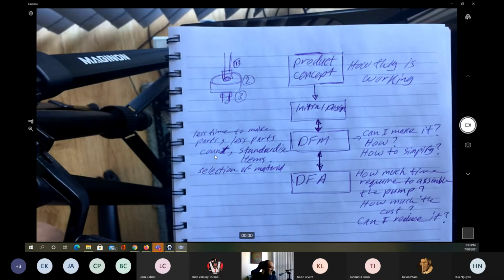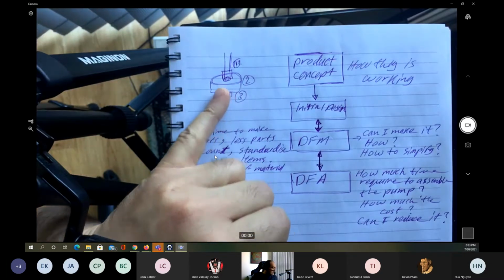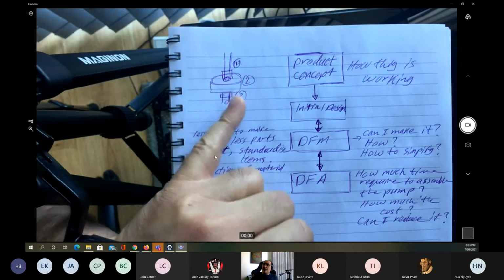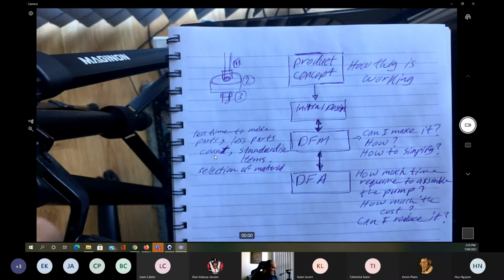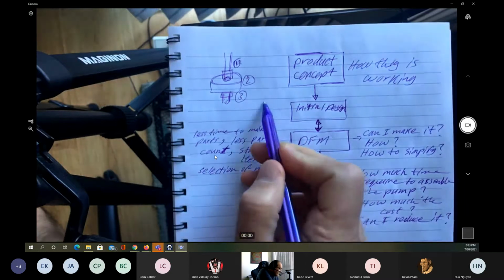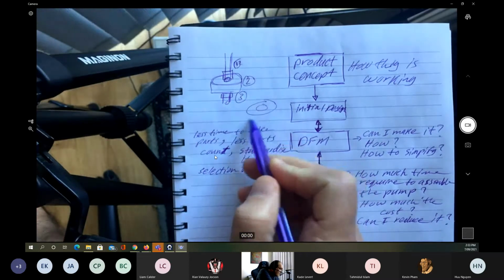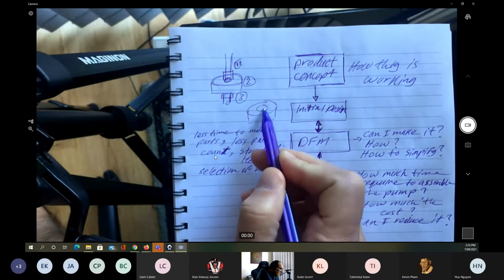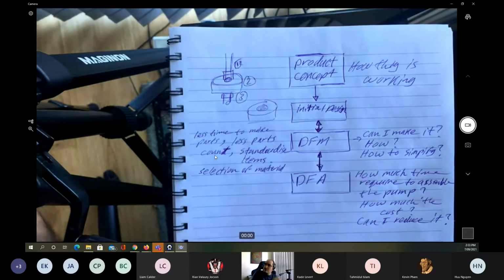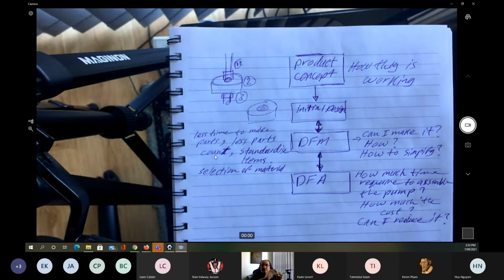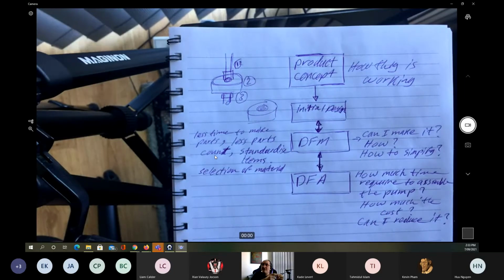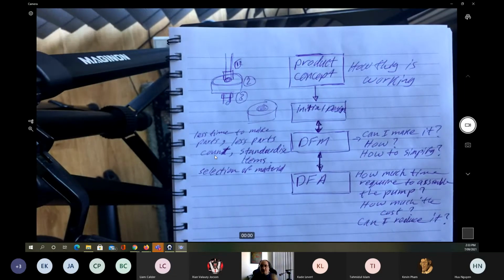Or I can make a design where the valve itself is going to have internal thread. If I get to have internal thread in the valve, I mean the whole hole here, I can make it threaded. So in that case, I don't use the two nuts, and simply rotate it over the shaft that's going to be sitting in.